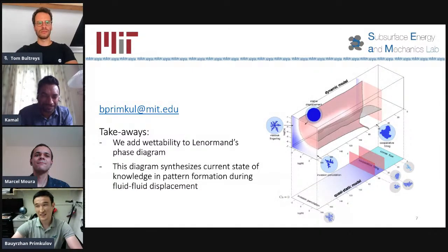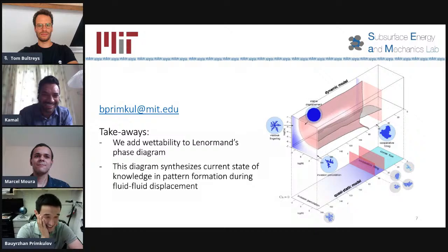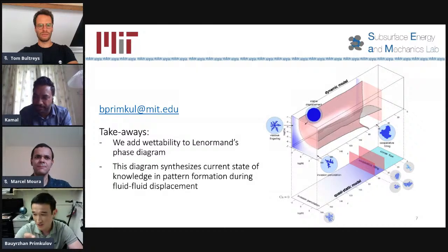Yeah. Enrico, nice to meet you. Really nice paper that really motivated some of the early work here. The way we define the activity index is as the fraction of pores that have appreciable flow rate. We take all of the pores and threshold the flow rates, which is a bit arbitrary, of course. Then you take the fraction of pores that meet that threshold.